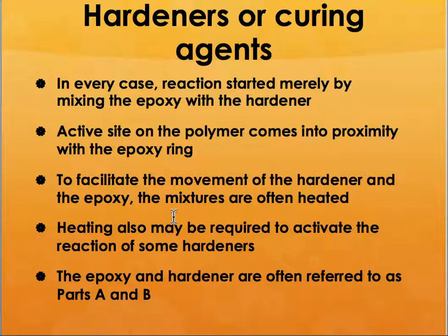When the active site on the polymer comes into proximity with the epoxy ring, it will start reacting. In order to facilitate that reaction, you heat up the reaction, which is part of the curing reaction. Heating may also be required to activate the reaction of some hardeners. The epoxy and hardener are often referred to as part A and part B. So almost all epoxies are two-part epoxies.